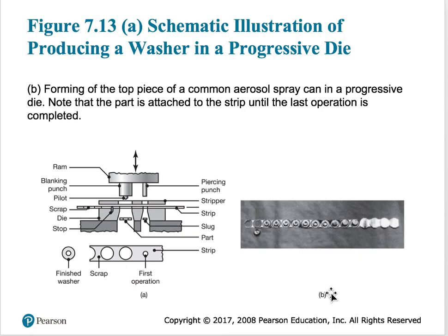It is done in multiple steps, cut using a bandsaw. Then you can also have flame cutting, using an oxyacetylene torch. You cut that if you're doing shipbuilding or very heavy construction operations, so you may use some kind of flame cutting operation.